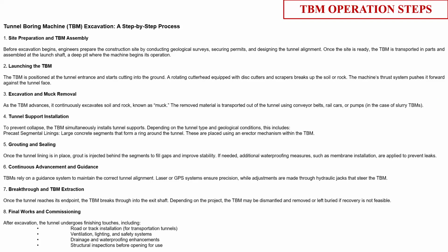It is excavating the ground. The ground that is excavated goes into the excavation chamber. Then you are removing it by the conveyor belt, and simultaneously you are installing the support. So at the front shield end, excavation is happening. At the rear shield end, the supports are being installed.